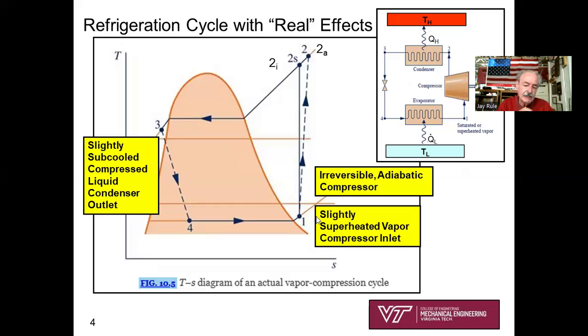So you'd have to have some idea of about how much superheat, in degrees C or degrees F, is going into heating the refrigerant up slightly above the temperature of saturation at P4 equals P1. So that's a second, very subtle part of analyzing a real refrigeration cycle. And the third one, it's really pretty easy.